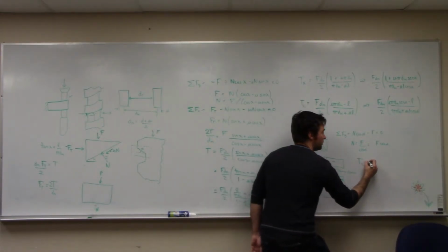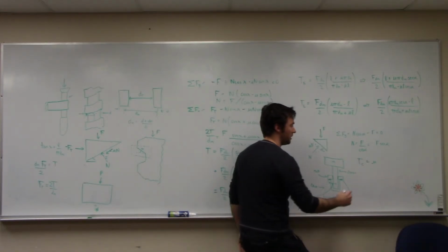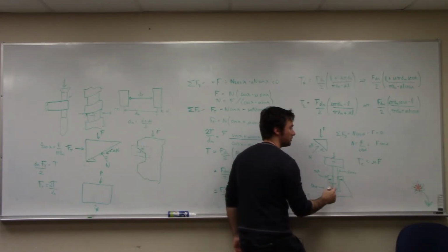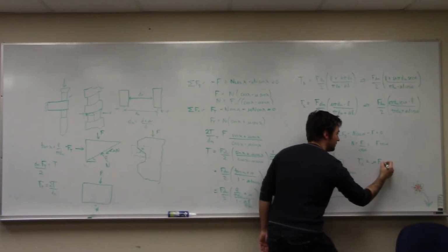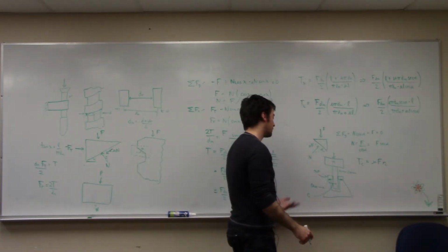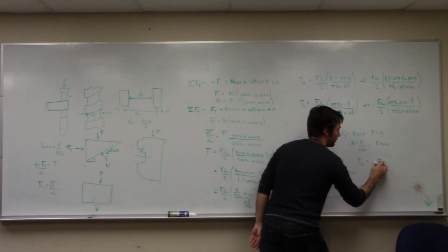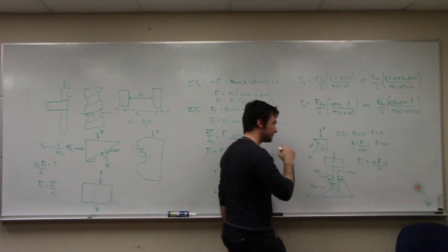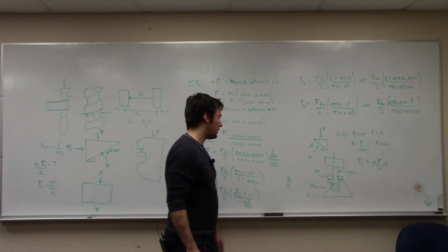So this torque is just mu times whatever, well, the force that it has to resist is just F, whatever force that I'm applying down, or the weight of the mass, etc. Mu F times the radius of the collar. The radius of the collar is sometimes put in terms of a diameter. The radius of the collar is diameter over 2. So let's change this to dc over 2. And so that becomes pretty simple to model.